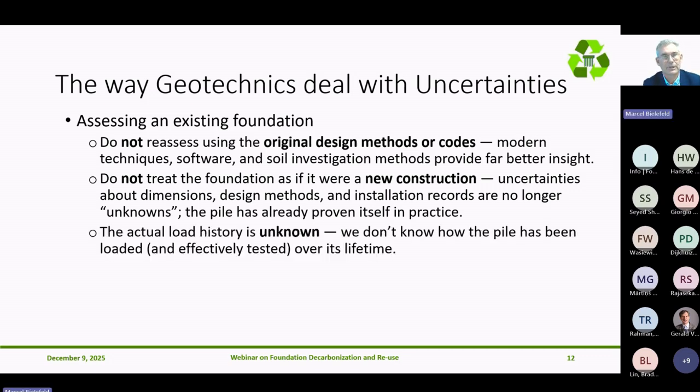And third, if we assess an existing foundation, we have to keep in mind that although we think the pile has proven itself over time, over decades, it's there, the actual load history is still unknown. We do not know up to which level the pile has been effectively loaded and thus effectively tested over its lifetime.